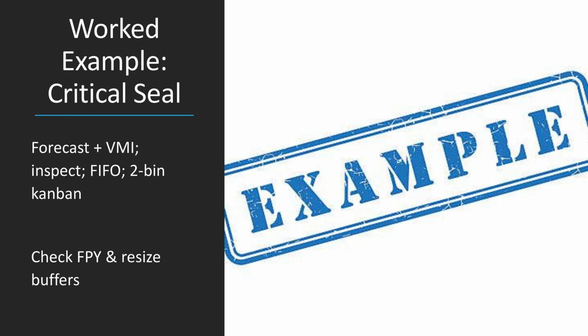Inbound logistics. I pre-book receiving slots. On arrival, I check packaging integrity, verify lot and expiry, and fast-track the lot to incoming inspection. I sample per plan, verify critical dimensions and hardness, and record results. Non-conformances, if any, go to quarantine, otherwise they are released for put away.